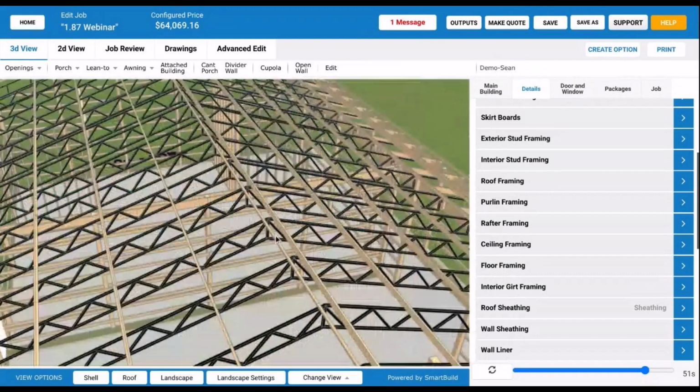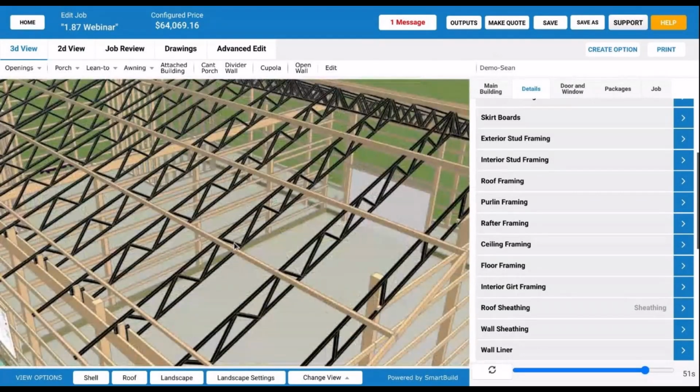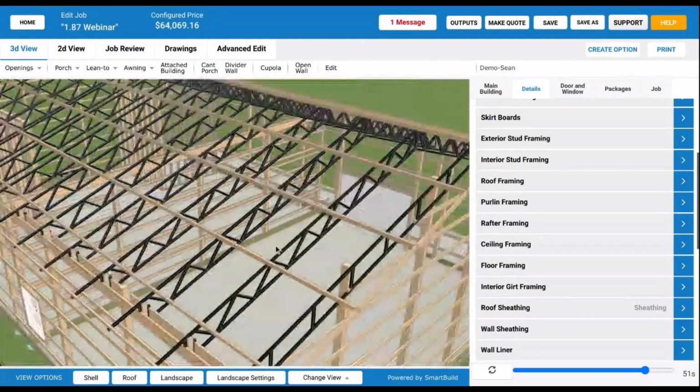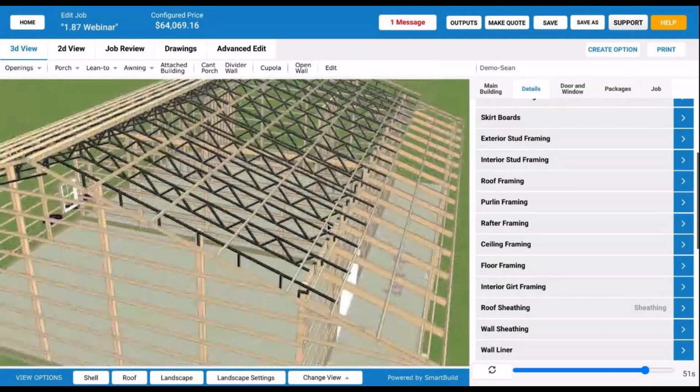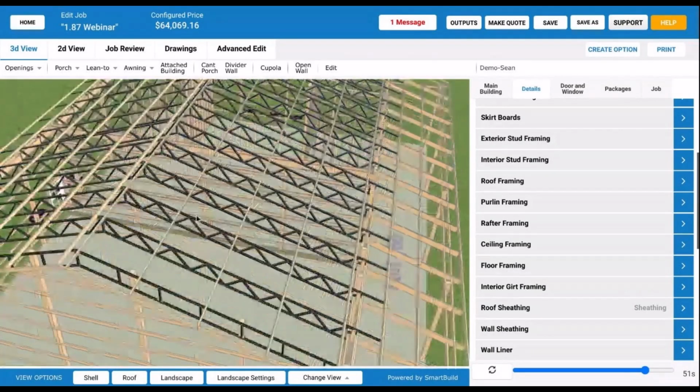Oh, that's a steel parallel chord truss. Yeah. Oh, do you have one? If you took over the screen, you could show people. I think Royden's here, got it now. But it would look just like this except orange and 2x4 material. There's nothing crazy about what it's going to look like. It just would look like a finished truss. It would show the web members and even the connector plates for the wood trusses.